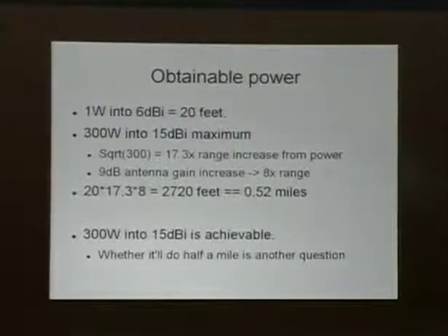That's still kind of a long way. 300 watts into 15 dBi is achievable. That, as I said, suitably motivated group of hackers could put that together relatively easily. Whether or not it'll do a 0.5 mile is another question, but at least we've got some numbers that seem to support that theory at the moment. Incidentally, if anyone is a ham radio operator and can prove to me why this won't work, I'd love to talk to you.